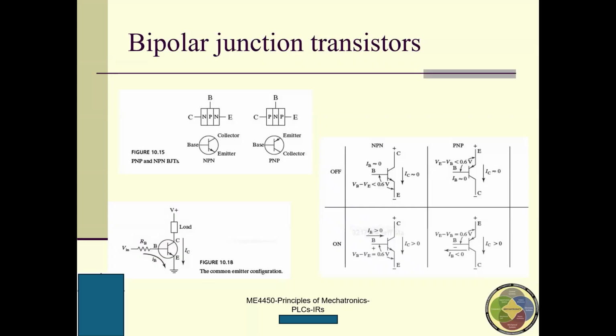You got it. So here is a very simple one. Here is a ground. Ground means I just treat this as 0. And VIN is the input voltage. If this input voltage is very low, how low? As long as the voltage difference between these two terminals is less than the threshold value, in this case 0.6 volts, there is no current. Right?